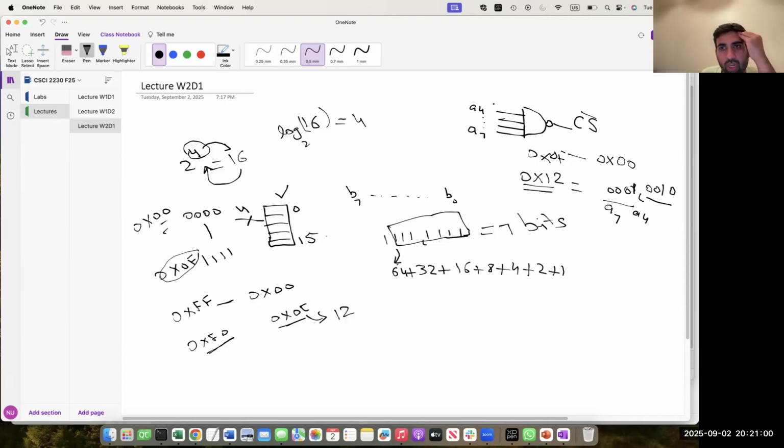So here I am putting 1. Oh, sorry. Here we also have bubbles. So here I'm putting 1, 0, 0, 0. If it is 1, then based on the NAND operation I will get an input of 0. If any input is 0, output will be 1. So the memory chip select will be not selected.